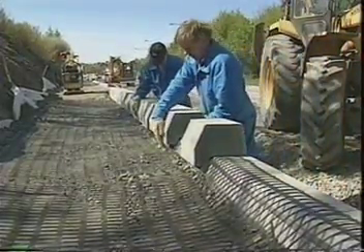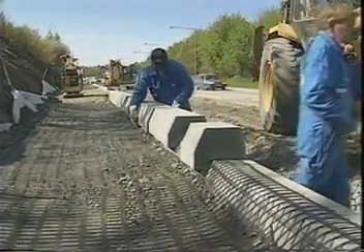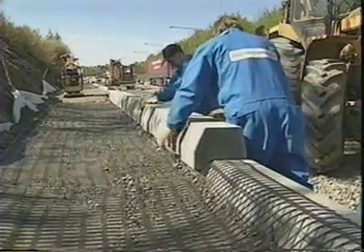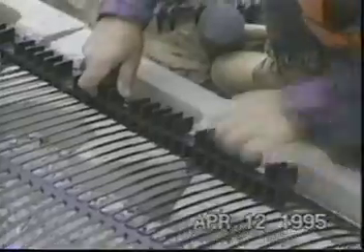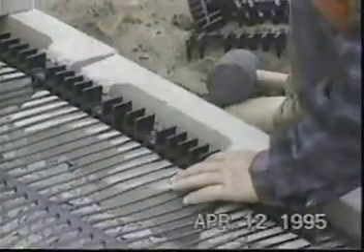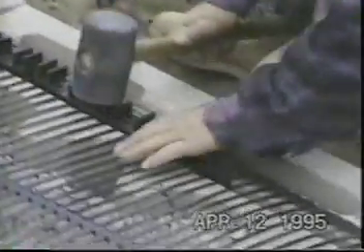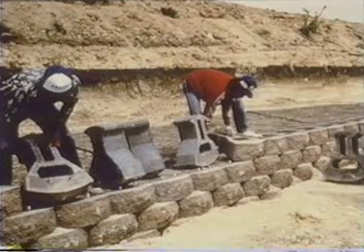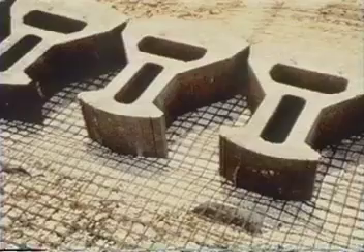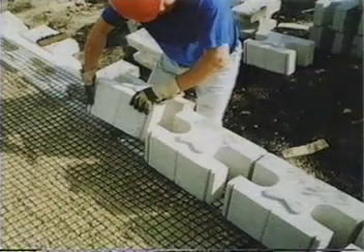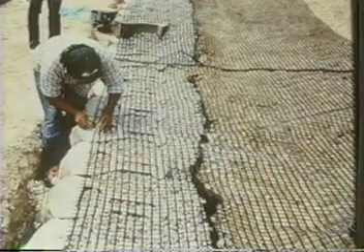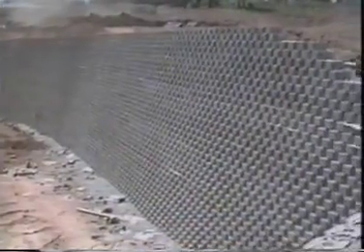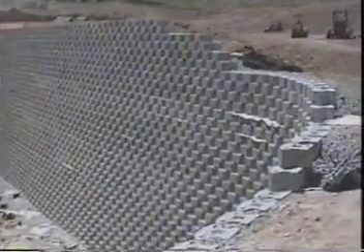Segmental blocks of various kinds can be used with strip reinforcement, but are most commonly used with geotextiles or geogrids, which are generally clamped between courses of blocks. In this system, polyethylene connectors join the facing to the reinforcing grid. To resist the shear that occurs between horizontal joints, blocks are usually manufactured with cast-in shear keys or shear clips, or to accommodate dowel bars. An extensive variety of modular systems is available.